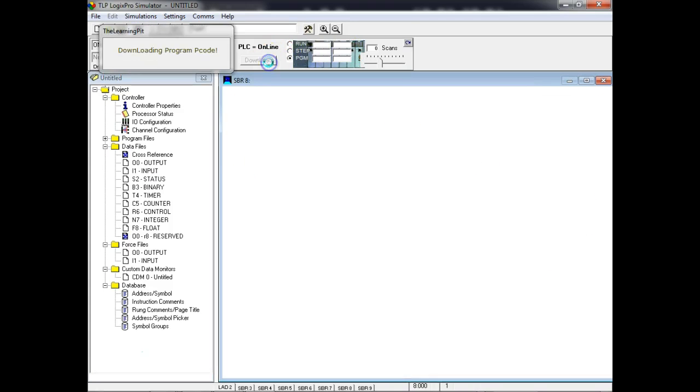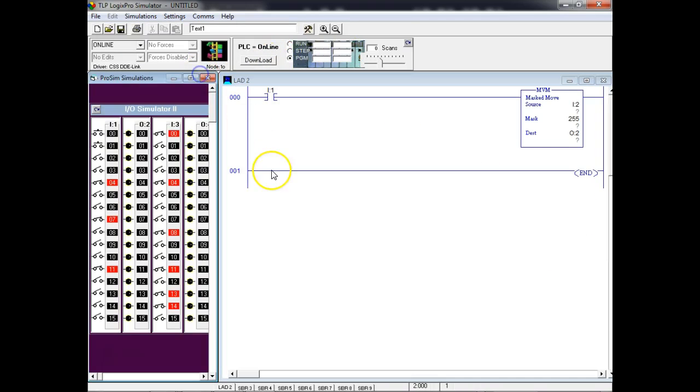Okay, so go down this. So what we can do is we can see this work instantly. So you said we had an X and converted over to decimal? Is that what happened? Yeah, 255. I entered in hex. Allen Bradley's RSLogix 500, we can enter it in different bases, but as soon as it does it, it's going to do it in decimal. So if you want to keep up with these, you need to write them down.